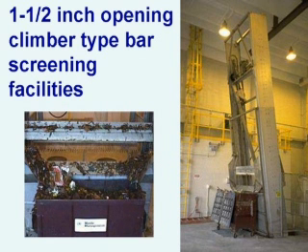As the water backs up, it goes over a weir, under a baffle and over a weir. That baffle wall is shown by that guy's yellow hat there. And there's also a vortex valve at the upper surface level that skims the solids off the surface as that water is backed up and it's caught in that chamber there.